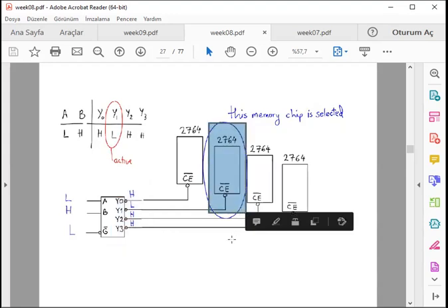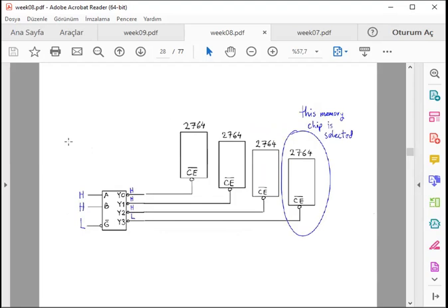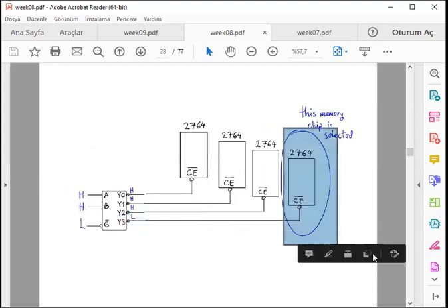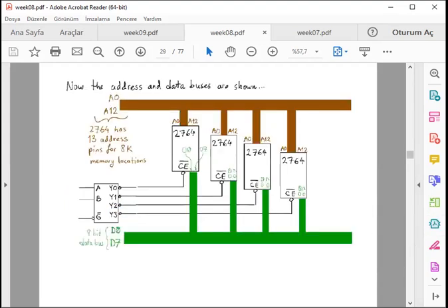So this is the particular memory chip selected to operate, ready to receive inputs and to yield digital information at its output. Only one chip is active. Like this one: enable is low, so the decoder is operational, and due to the selection bits being high, we select the Y3 output and the corresponding memory part.